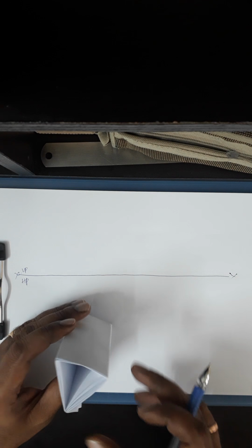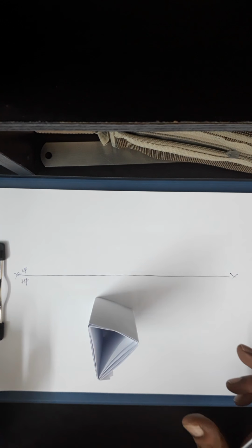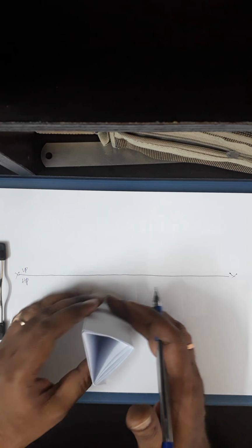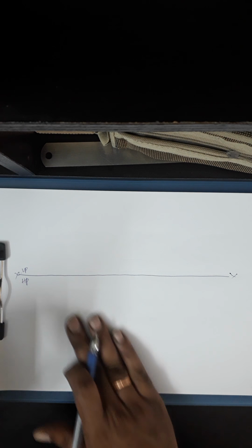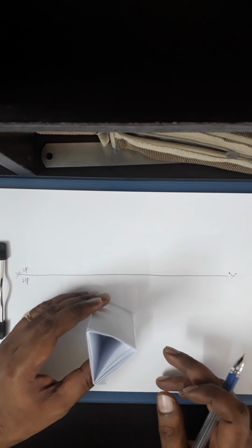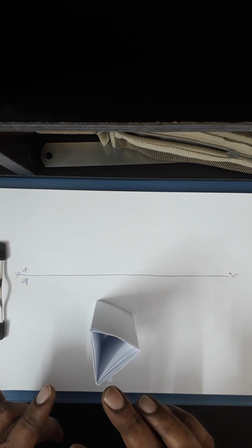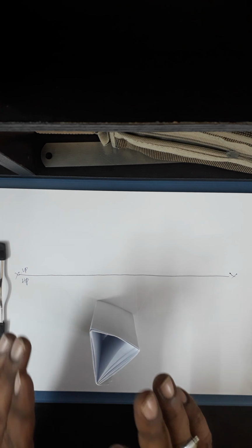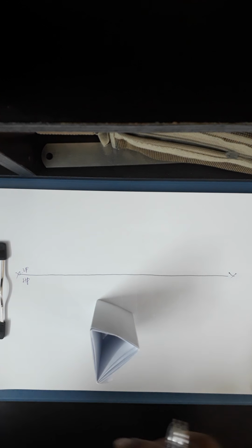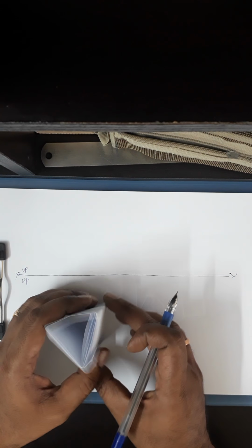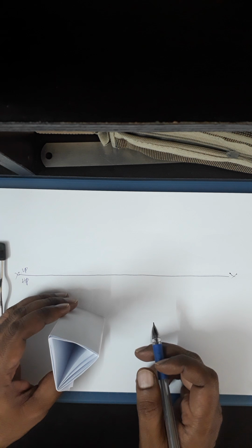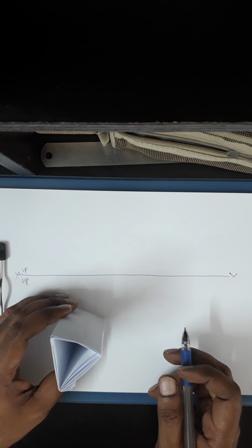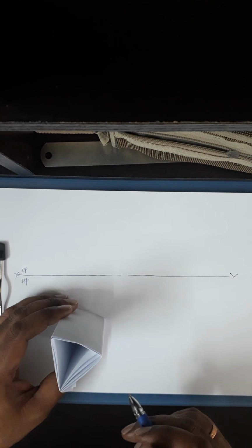Okay. So if we keep the solid below this XY line, this is nothing but your horizontal plane and this is the vertical plane, right? So it's nothing but the solid is resting on its base on HP. So the prism is resting on its base on HP. So when I want to keep the solid, again if I want to give the axis of this solid to incline with HP,